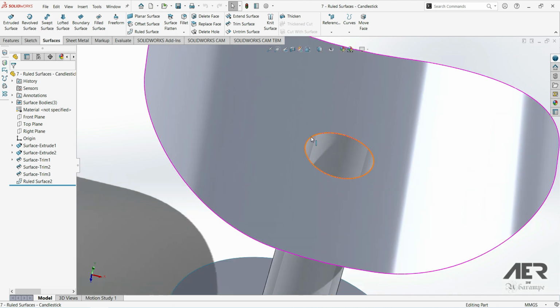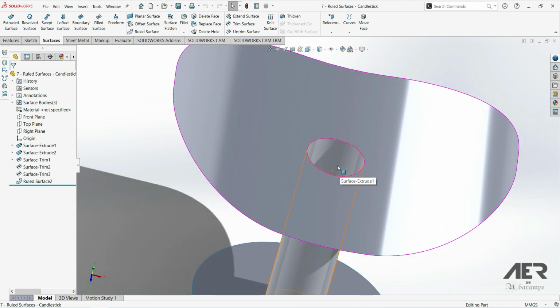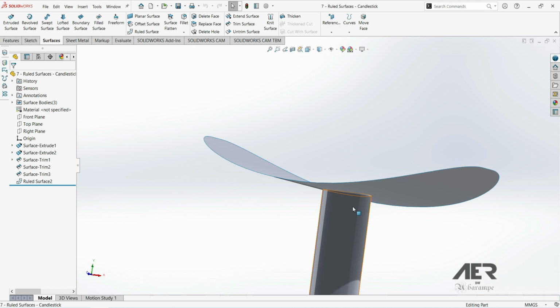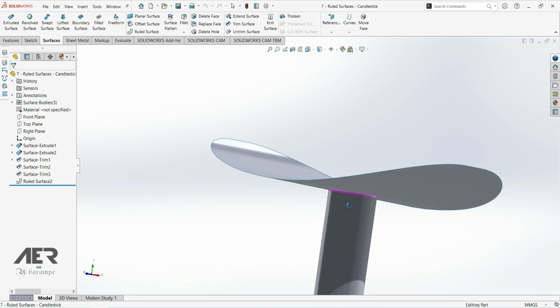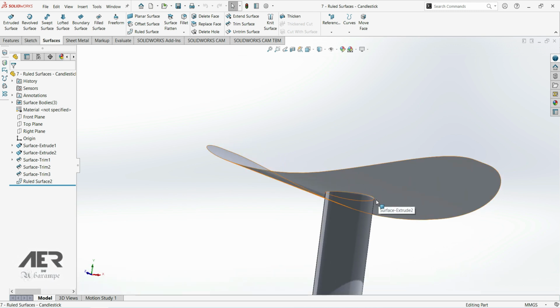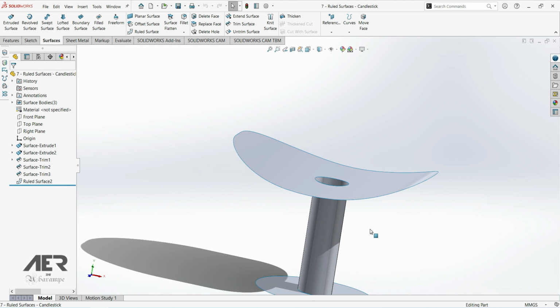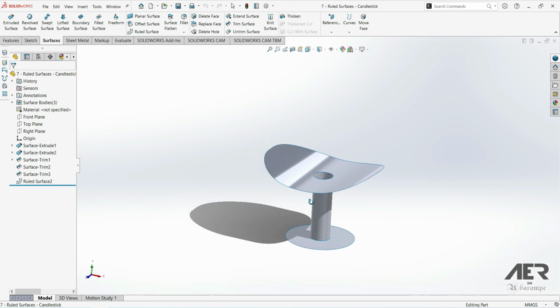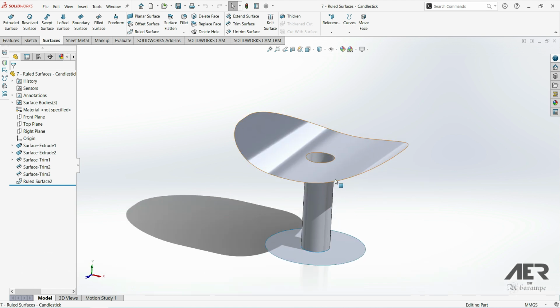So let's say we wanted to fillet this top edge here. If this was a solid model, we would actually take away some material when we make the fillet there. But we can't really do that in this case because we've got no thickness to these surfaces. If we took away an edge there, it would just leave us a gap. Luckily there's a fillet tool, especially for surfacing.